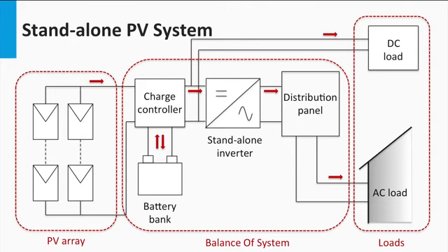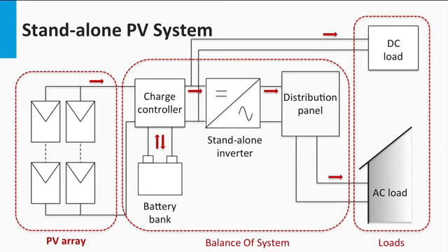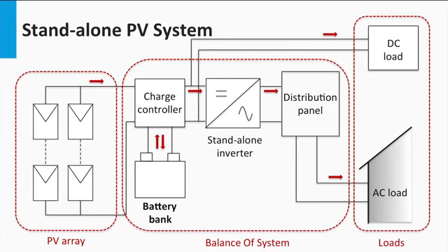As discussed before, the standalone PV system has these important PV system components. The PV array is an interconnection of modules that supplies the required photo-generated power to the system. The power rating of the array is determined based on the load requirements. The battery bank is the lifeline of the standalone PV system, as it greatly increases the usability of the PV system. Without the battery, the system would be unable to meet the load demands outside the available daylight.